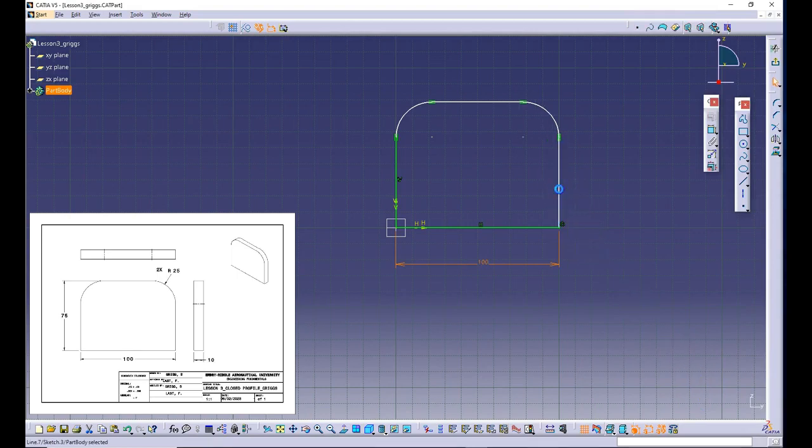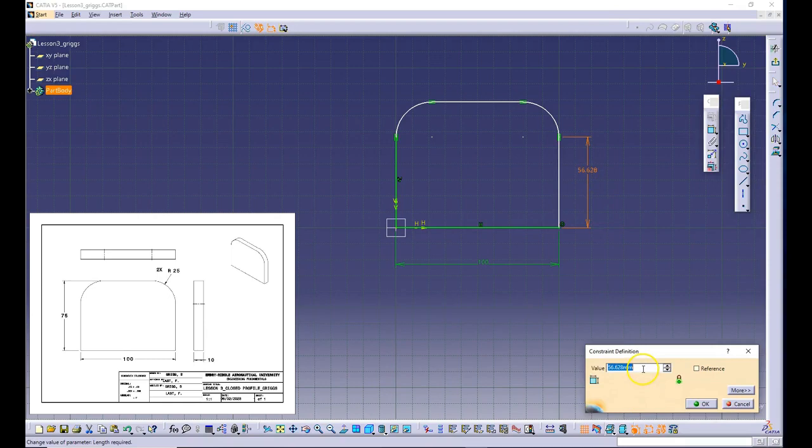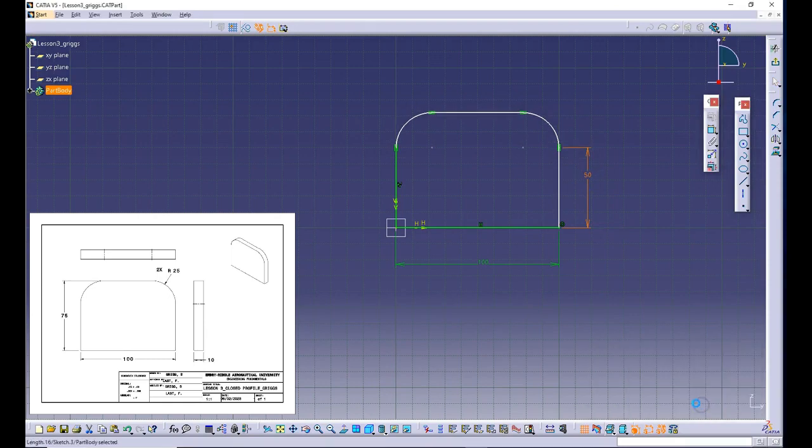That being said, if I wanted to, say, create a constraint on the right-hand side that was in inches, I could do that. I wouldn't really want to, because you always want your variables to be consistent across your drawing, but 50 millimeters instead. Now notice that when I created the 50, it didn't turn all the way green yet. And you can see on the left-hand side here that I have a V showing that it is vertical. So I don't have that on my right-hand side.